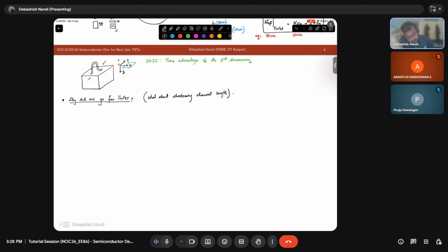So as length decreases, threshold voltage decreases, I off increases. Do you agree to that? Yes, sir. So higher static power dissipation.